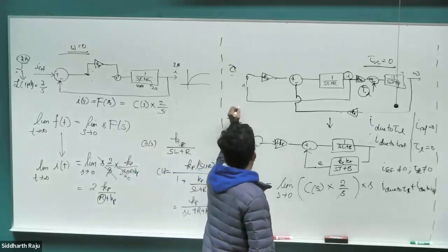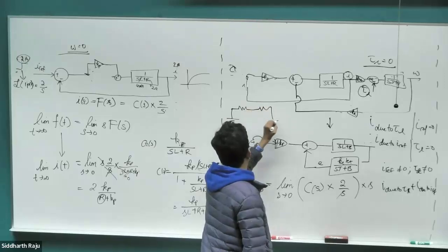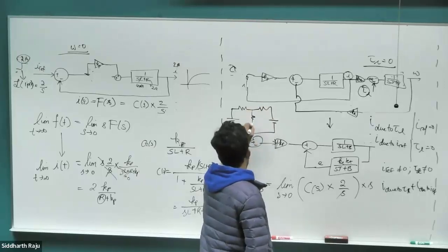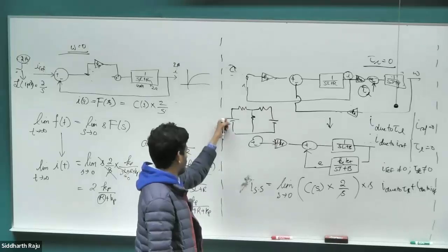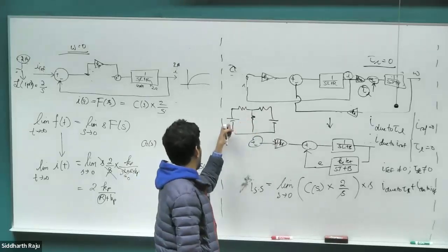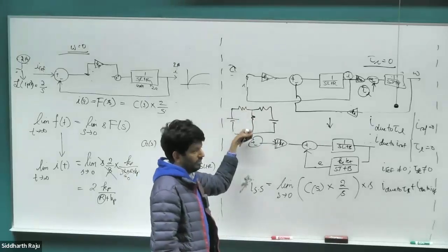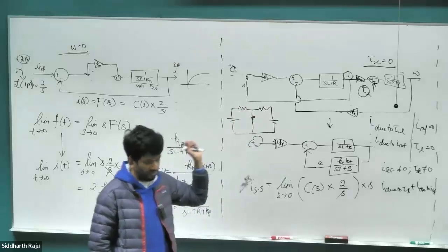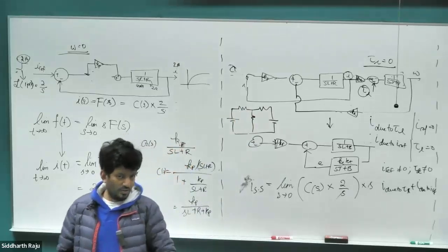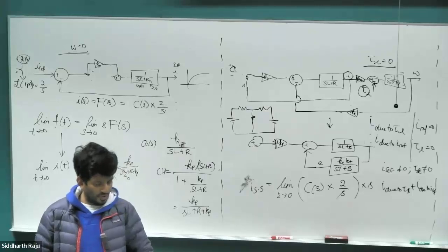We had a voltage source like this, and another voltage source on the other side. The way you always short this, find out the current through this network. Short this, find out the current through this network. The net current is the sum of the two. Only possible in linear circuits. Okay. Any other questions? Okay.